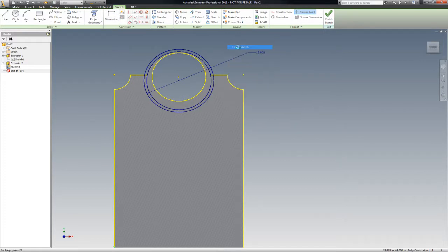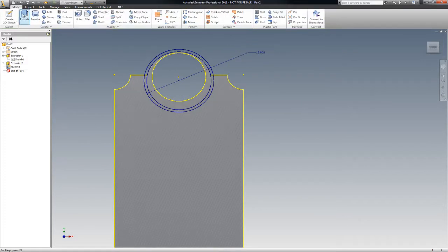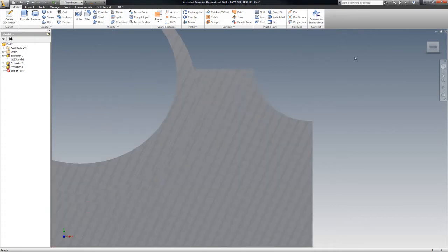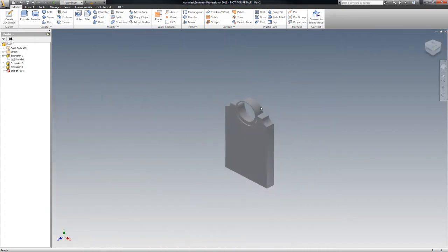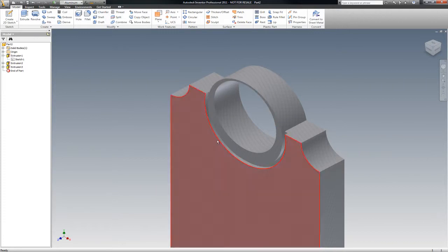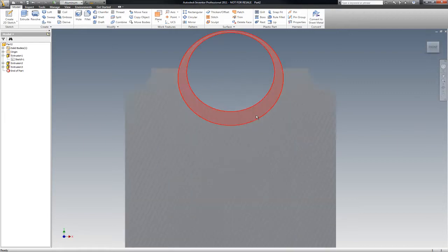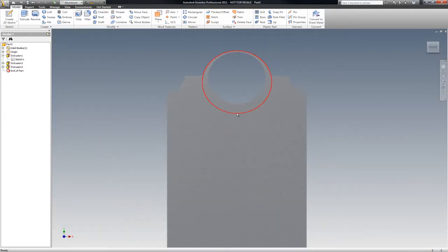And then I'm going to finish sketch, and let's see if this will let me extrude that, cut that in. I want to go to my cut plane here. So I want to pick this and go to cut, and I want to go to about 0.5 and go OK. And let's see what happens. And there you go. You can start to see that I've etched into it, and that was my goal. Okay. So then I'm going to spend a few more minutes drawing, and then I'm going to take a pause, and then I'll come back when I'm doing the text.